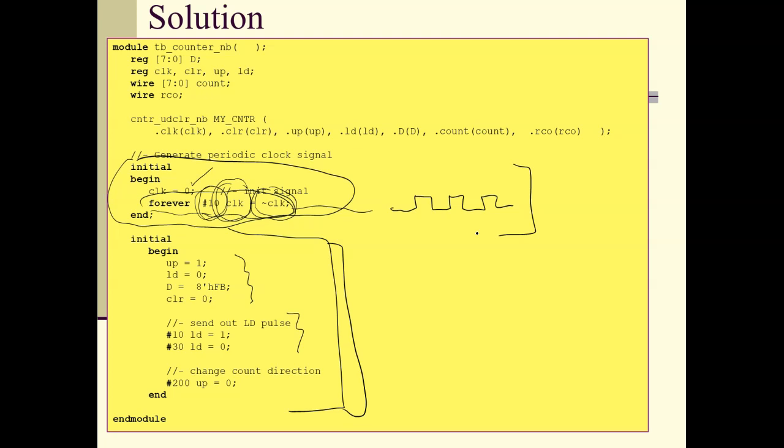But you could have initial blocks for any set of signals you want, just to make your test bench simulation more readable. The only other comment is that it uses horizontal instantiation, which you don't want to do. Everything assigned from those initial blocks is a procedural assignment, so those signals need to be declared as regs.